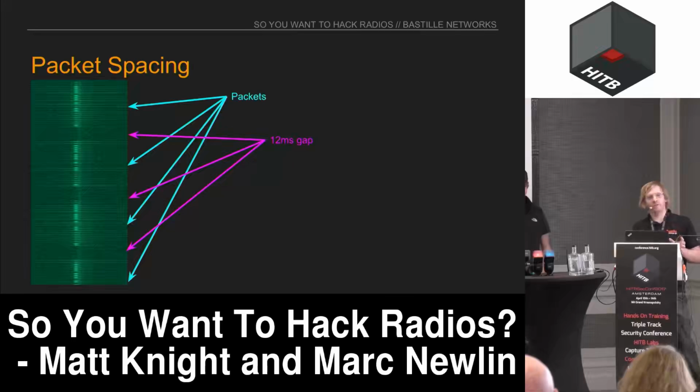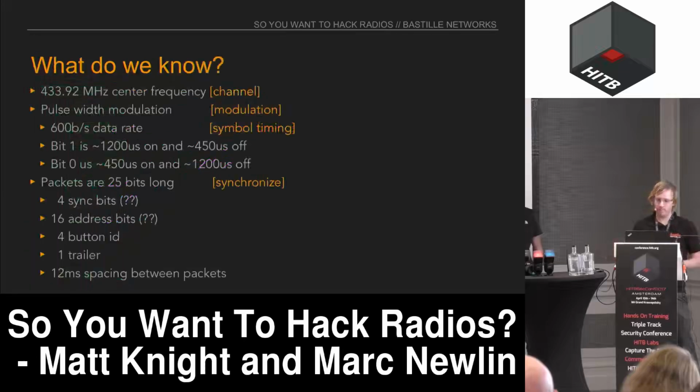And another thing that we have to consider is the packet spacing. So when you hold down a button on the remote, it sends these same packets over and over again. So it'll send a packet, wait 12 milliseconds, and then send the packet again. And it will just keep doing this as long as you hold down the button. The reason is that there's no way for the LED strip itself to reply to the remote. So in order to make sure that the commands are received, it just spams them continuously.